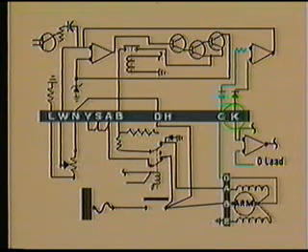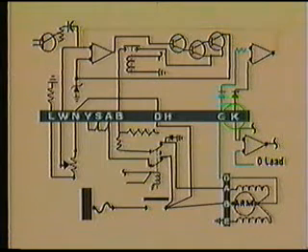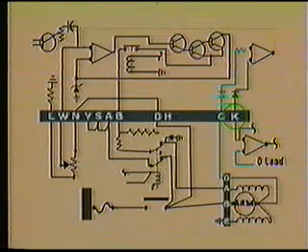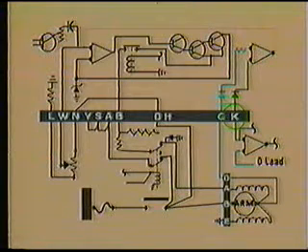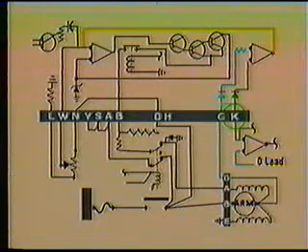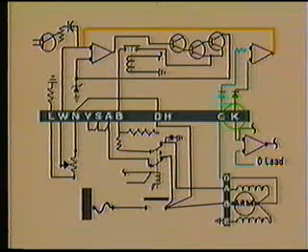While the precise operation of these units is not important, suffice it to say that by using the inputs provided, each operational amplifier in each control panel will provide an output consistent with the load sharing status of its generator. If it senses that its generator is carrying more of the load, its output will be reduced. If it senses that its generator is carrying less of the load than the output of the other generator, its output will increase.